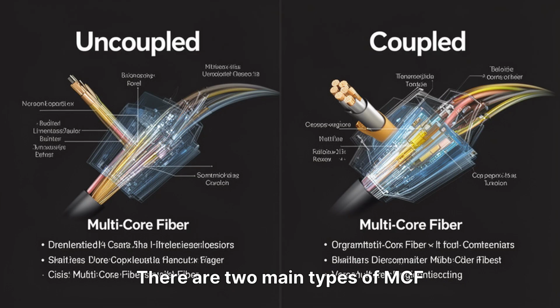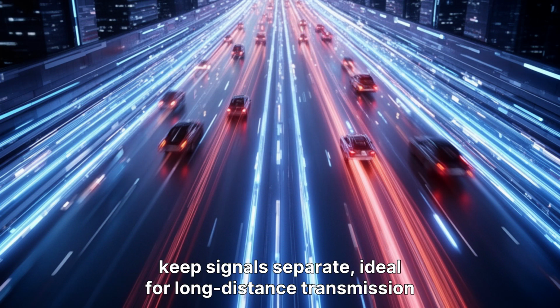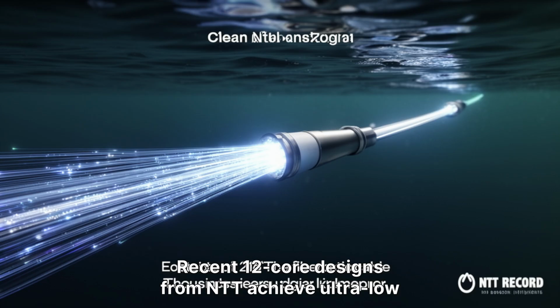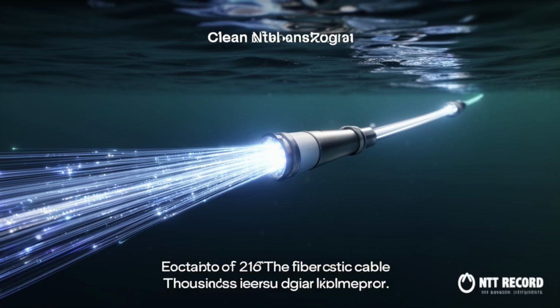There are two main types of MCF for SDM: uncoupled and coupled. Each serves a different purpose in the global network. In uncoupled MCFs, cores are isolated to keep signals separate, ideal for long-distance transmission with low interference. This is like having multiple lanes on a highway with barriers. Recent 12-core designs from NTT achieve ultra-low crosstalk, enabling thousands of kilometers of transmission without signal degradation. This is the gold standard for global backbones.